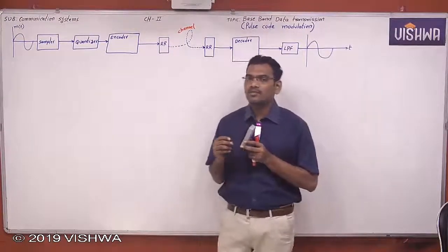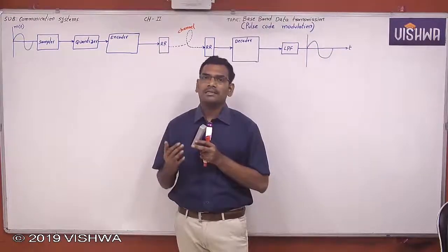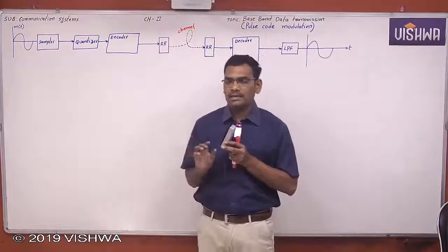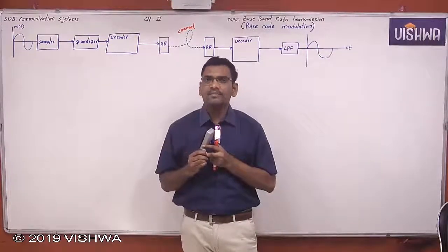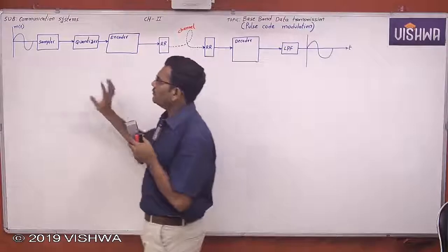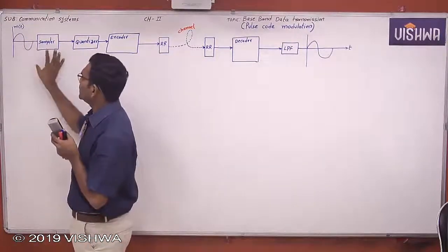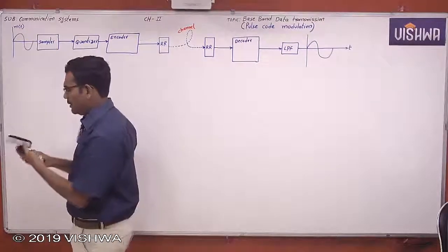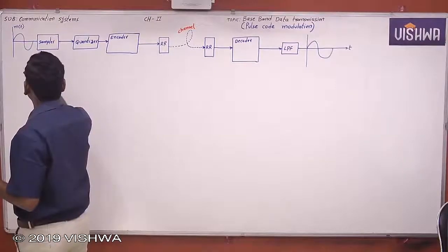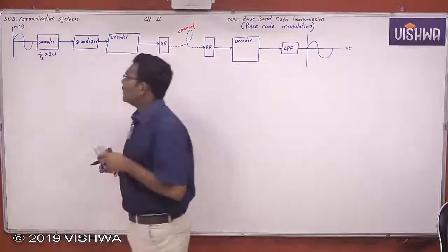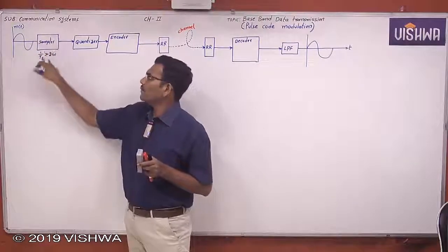We always go for oversampling, which is good, and successful reconstruction is possible. All these things you already covered. Never do undersampling, because the aliasing effect will take place. The minimum sampling is called the Nyquist rate, also called ideal sampling. The best sampling rate is oversampling, which means a sampling rate greater than the Nyquist rate. Now, this part you completed, only the sampling part.